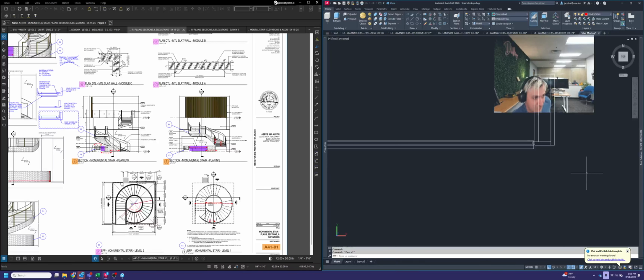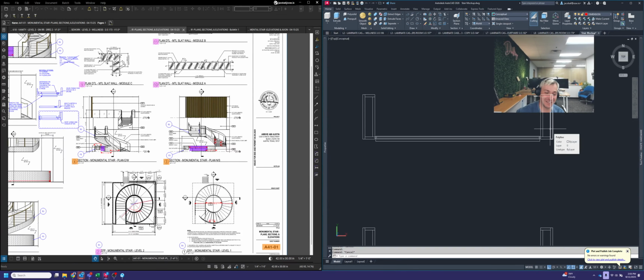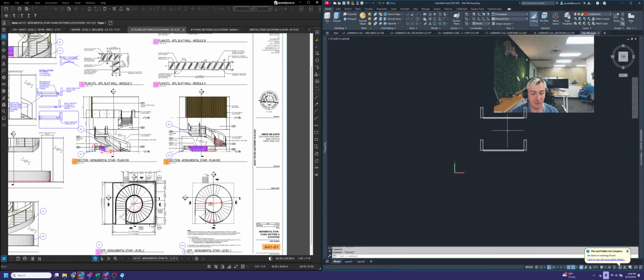It'll actually sweep it as a surface, which I know you guys pretty much all know anyway. But just a reminder, because it's easy to do that and forget. So anytime you're sweeping anything, it always has to be closed polylines. With that being said, you can either use BPOLY, or you can use J for join and just close your polylines that way. But you always want to start by drawing your 2D section view first.